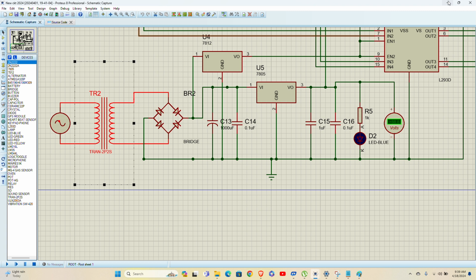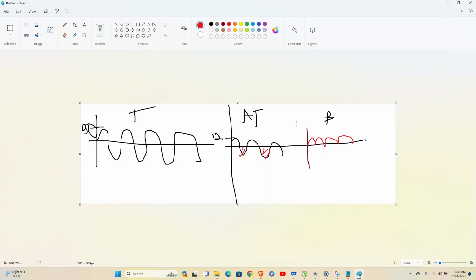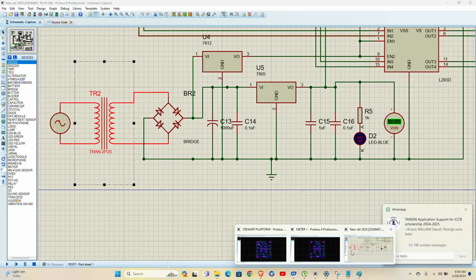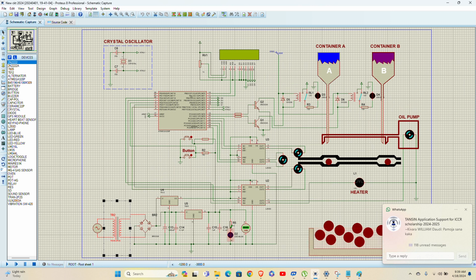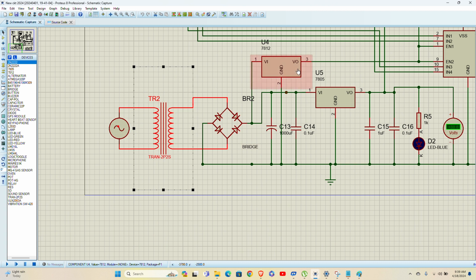These other capacitors support these regulators. So we have two regulators, I will explain later. So after the capacitor here, what will remain? It will be like this. The voltage will go up, but when it tries to slow down, it will be negated by the capacitor, because the capacitor will have charge at that time. So these are the stages to rectify voltages in our project.